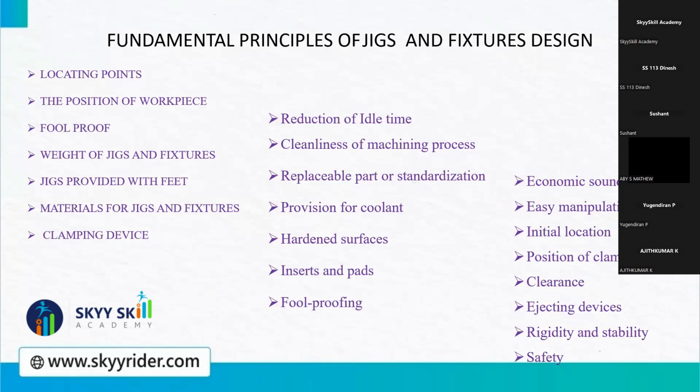And there are various material types being used for jigs and fixture. Okay, I will give you some names of different materials like MS, EN8 or OHNS. There are various materials; even nylon materials are being used, brass materials can be used. Okay, cast iron bodies can be used. There are various metals that can be used for the making of jigs and fixture.